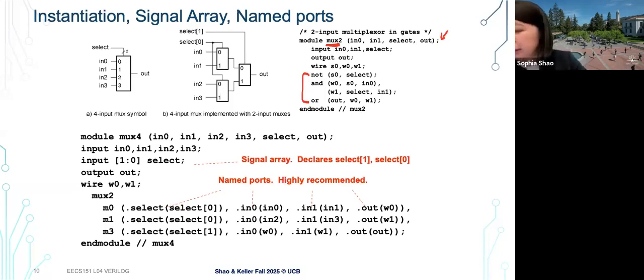One thing that is always useful is to think about how we hierarchically build a more complex system using the basic blocks. Once you have 2-input muxes, if I want a 4-input mux, I can reuse the 2-input mux and do selection hierarchically, and that will give me a 4-input mux with 4 input signals and a select to one output signal.